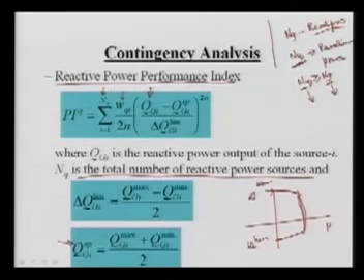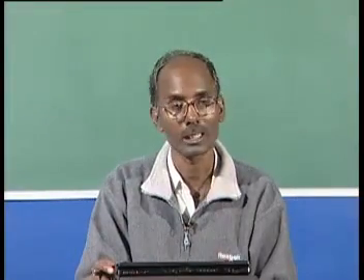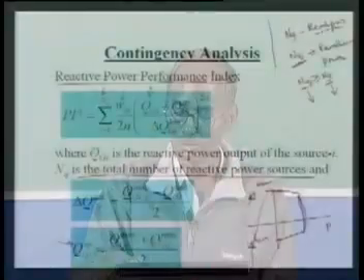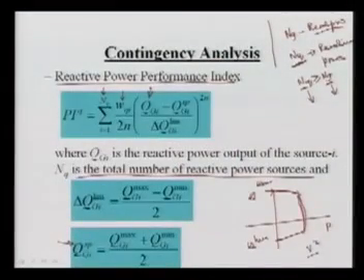But some of the devices, like a capacitor, will generate reactive power because it has no limit. It depends upon the voltage. How much does the capacitor generate? Its value here is V square into omega C. That will be the reactive power generated by a capacitor, simple.